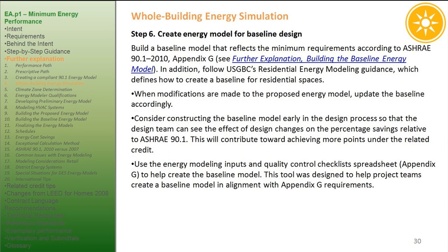Step 6. Create energy model for baseline design. Build a baseline model that reflects the minimum requirements according to ASHRAE 90.1 2010, Appendix G. See further explanation, Building the Baseline Energy Model. In addition, follow USGBC's Residential Energy Modeling Guidance, which defines how to create a baseline for residential spaces. When modifications are made to the proposed energy model, update the baseline accordingly.